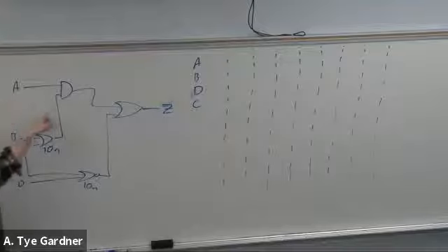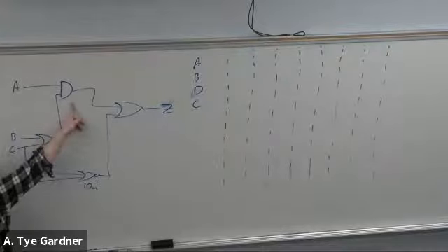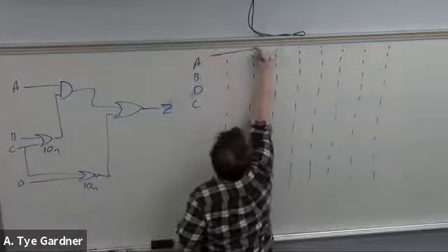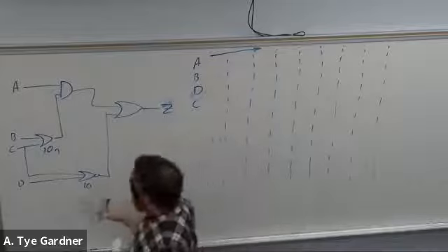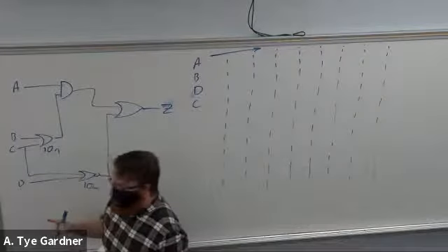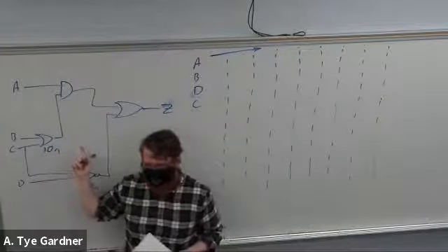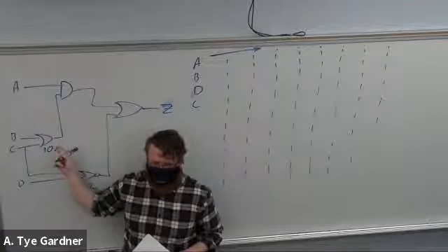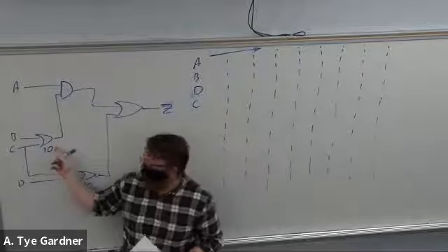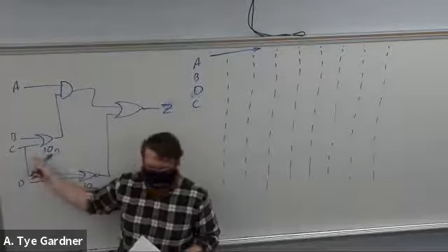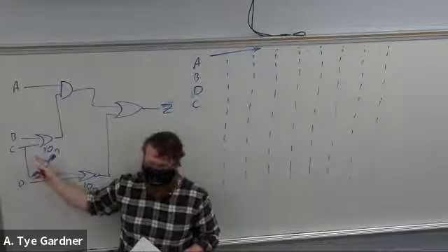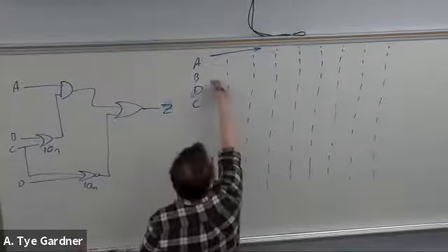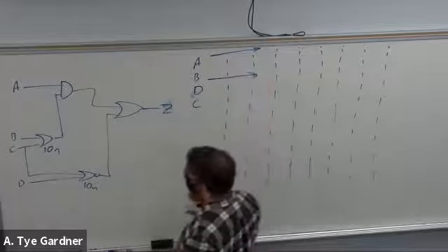Yeah, so A is high because it's an AND gate, right? That's how I prime it. So A is 1, oops, sorry, I was correct, 1 forever. B is going into an OR gate. How do I prime an OR gate? 0, right? Because if it's 1, no matter what C does, it doesn't change. So therefore, prime it with 0 forever.